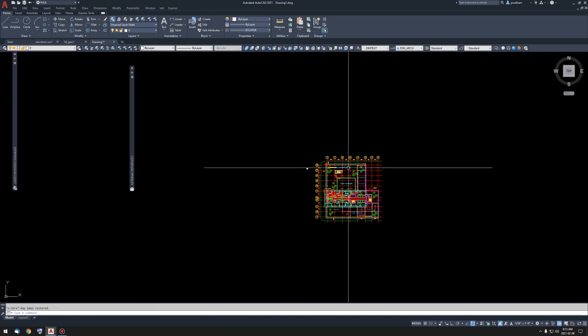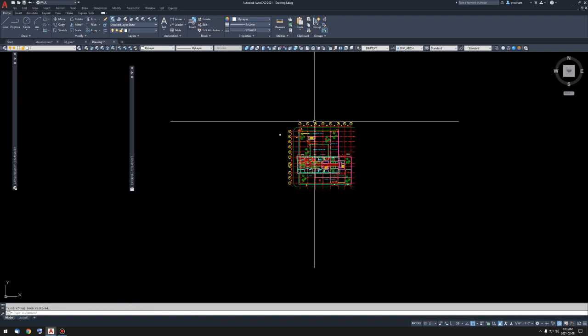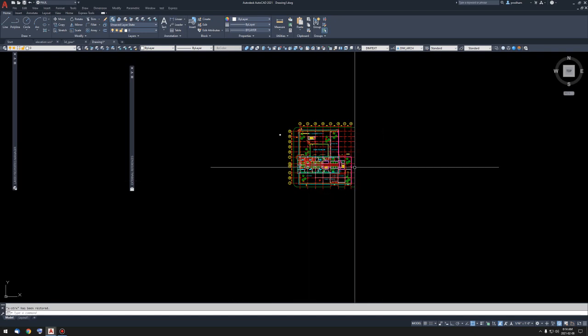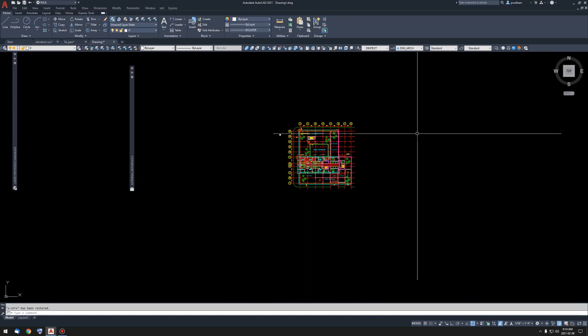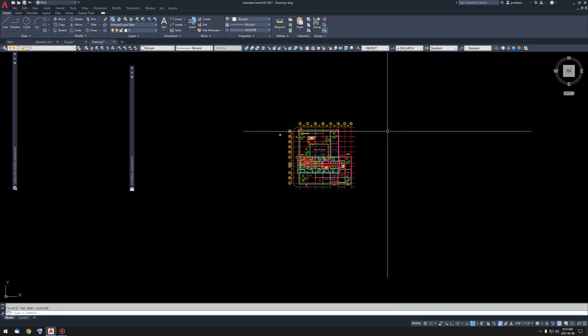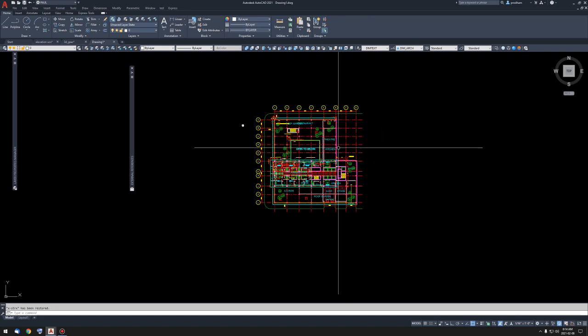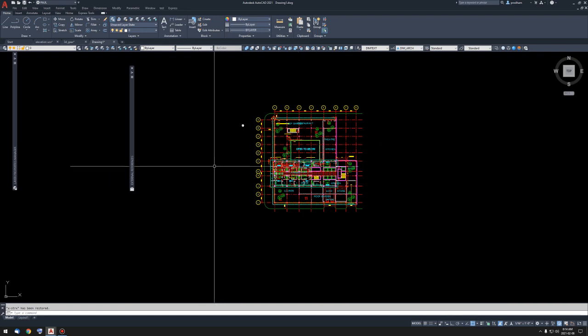Okay. Now, what we did in the other example, we talked about this traditional way of pinwheeling all the elevations from the plan. And like I said, that's nice, but you have to work with coordinate systems. An easier way to work on a lot of projects, this doesn't work for every project, but it's certainly going to work on this one, is the best elevation to draw right now would be the south elevation, if we were drawing the south elevation. In this project, we're drawing the north and then the west.